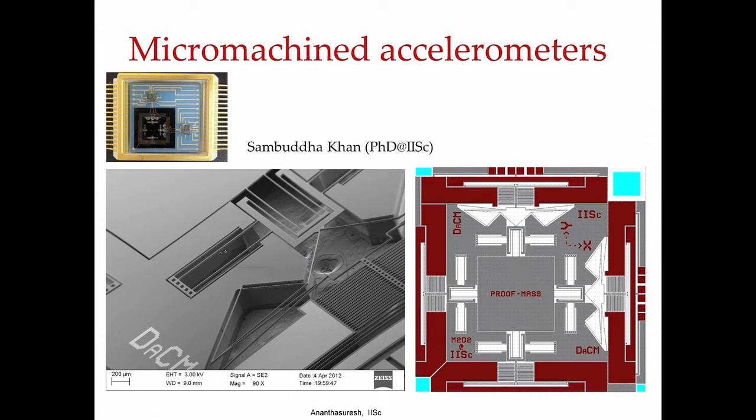And it is all done, you can see the silicon scanning electron micrograph here, and the width of these beams is typically 5 microns, or as small as the fabrication process allows. And the compliant mechanism beams you also see here are very tiny, and there is no assembly involved. So, you can have complicated compliant mechanisms made using photolithography.